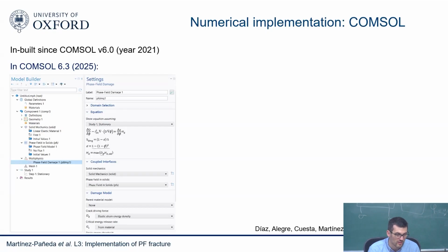But I think the reason why they became so popular is that they use this symbolic differentiation, where you don't have to implement things at the low level. You just define your differential equation, and then everything is taken care of. It's similar to FEniCS in that sense. FEniCS uses more the weak form, but here you just define the strong form, and then automatically the computer will do it for you. It will identify the weak form, it will then take residuals, it will take stiffness matrices, and so on.